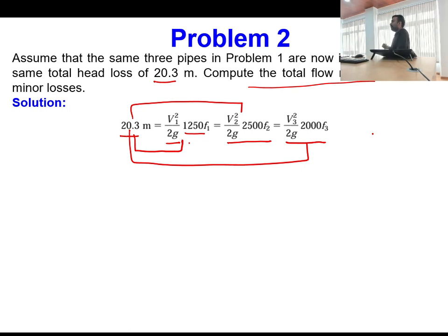The meaning of totally rough design is that the Reynolds number dependence will not come into the friction factor. The friction factor will be solely a function of relative roughness, and relative roughness is given in the question. So I can immediately go to the Moody diagram, and from it find the value of friction factor f1 for the rough design.